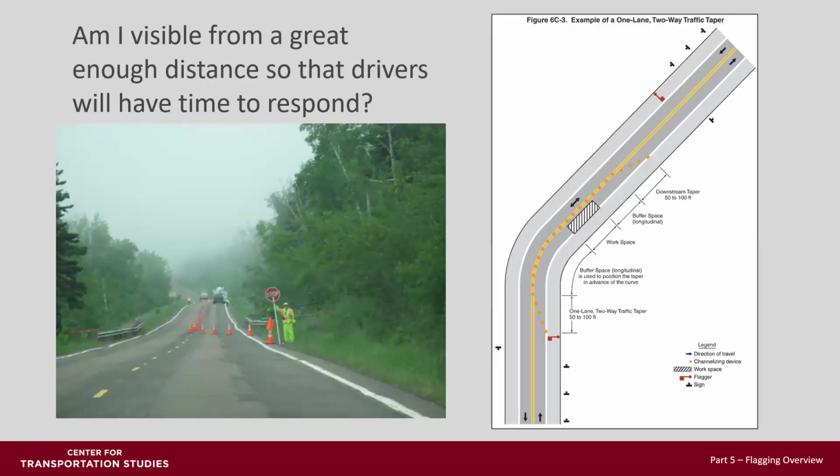Flaggers need to ensure they're visible and may have to place the flagging station further away from the workspace. Pay attention to your background. Are traffic control equipment and other objects camouflaging you? Is the sun low in the sky behind you, blinding oncoming drivers?